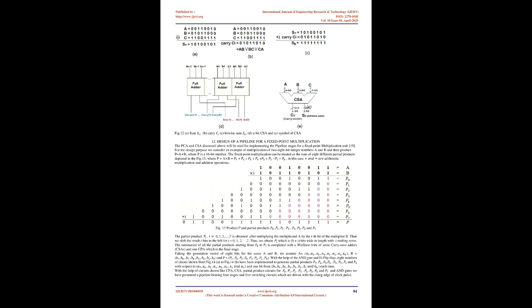8. Design of D flip-flop using logic gates. The flip-flop is a sequential circuit used for storing data from two stable states. A classical D flip-flop consists of 4 NAND gates and 1 inverter, shown in Fig. 8a. There are two inputs, D and clock, and two outputs, Q and Q-bar. The input-output relationship is shown in the truth table in Fig. 8b.